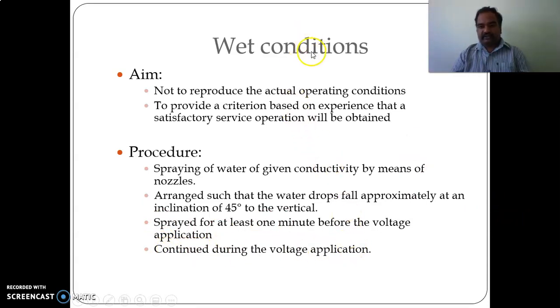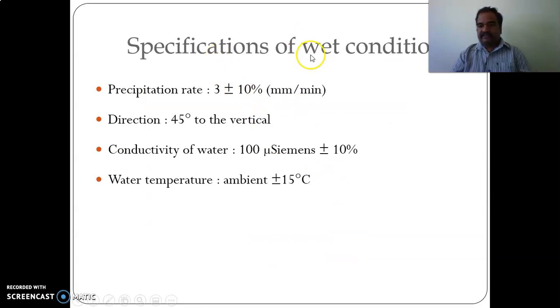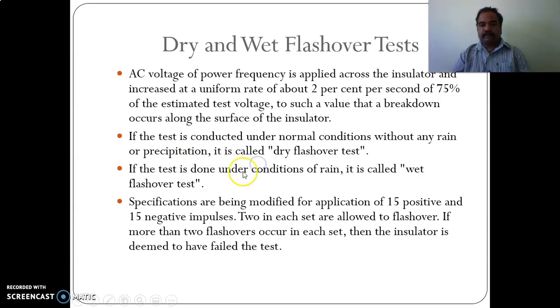Along with this, there is a specification of wet conditions as per the standards. See the precipitation rate, the direction of waterfall, the conductivity of water, and the water temperature. These must be as per the standards. So you are supposed to test your equipment for both dry and wet conditions.